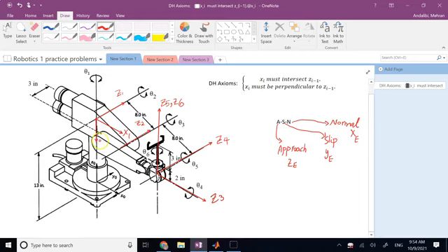All you need really is x and z, because that's how the DH is defined. The y's will automatically be aligned when you align x's and z's. But here, for more clarification, I show you the y-axis as well. So that's frame 1, that's origin 1.